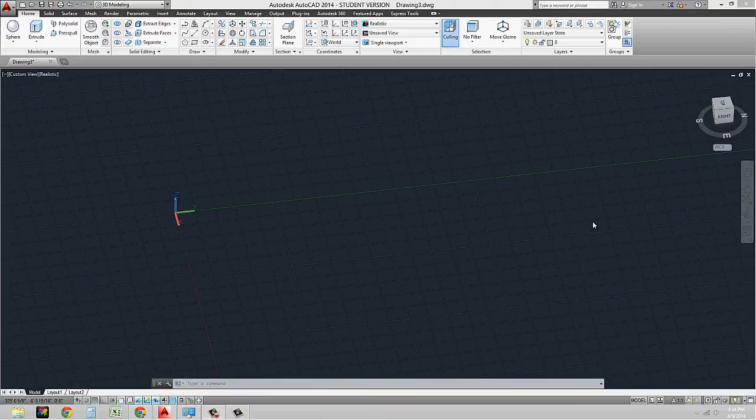As I said before, we can also create our 3D models using existing drawings or existing objects, and these next tools are going to be helpful in doing that. Traditionally, a lot of people advocate for students, or whoever's drafting in AutoCAD, to always use polylines, because it makes three-dimensional extrusion a lot easier. I can work with my two-dimensional tools in three-dimensional AutoCAD. It's not really three-dimensional AutoCAD, it's just introducing this z-axis into the model space that we've been using. I can draw on it like any other drawing we've been working with so far.